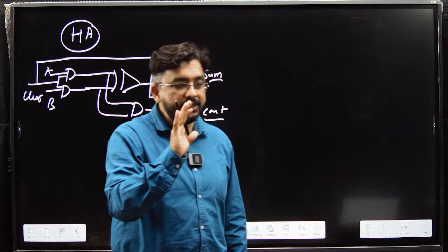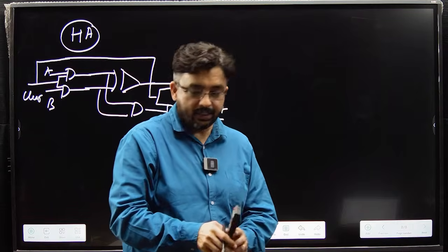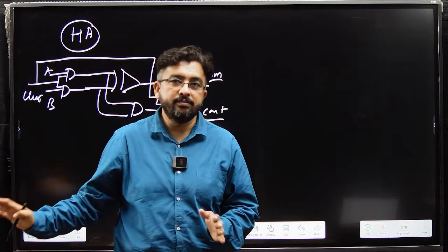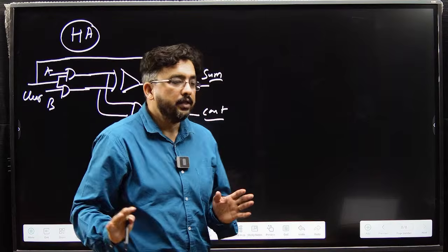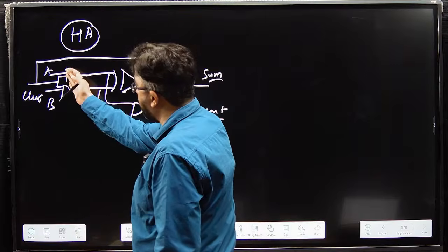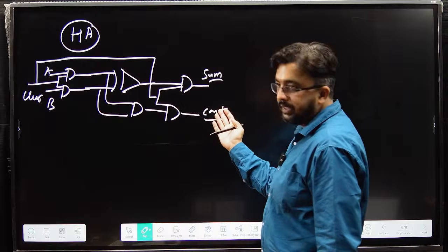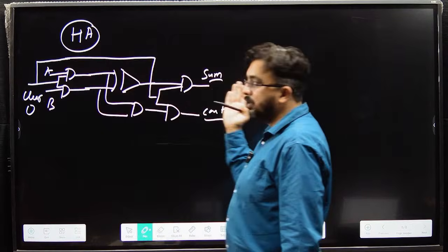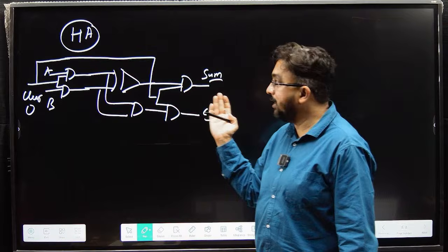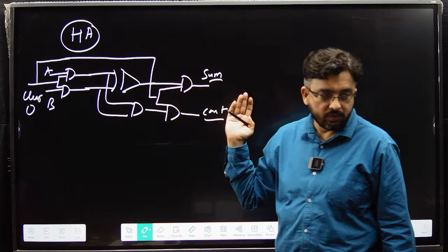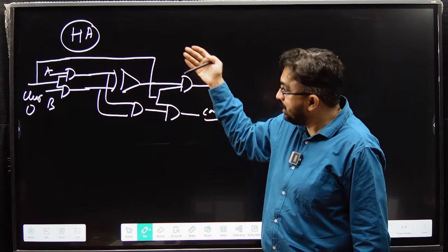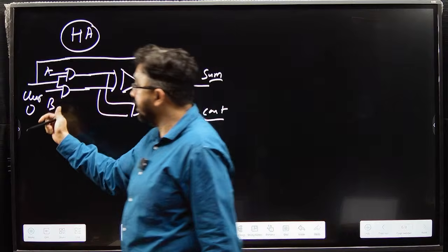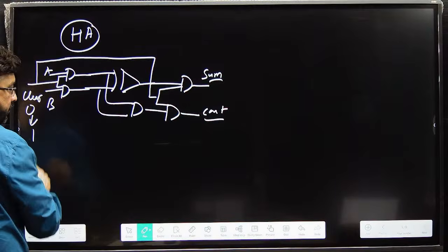I have control on each and every line. That is why I have used this clear. Every signal will pass through an AND gate, so whenever I give 0, the output will always be 0, meaning all the signals will be 0. Whenever I want my circuit to start working properly, I will make this clear go from 0 to 1. Then it will start properly.